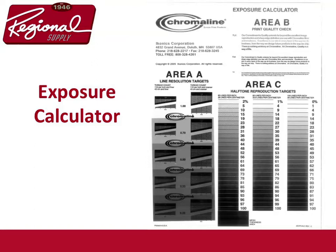Now, we have a lot of people ask, how long should I expose a screen? Well, it's really kind of a loaded question based off what kind of exposure unit you're using, how old your lamps are, what kind of emulsion you use, ProCap, how thick your ProCap was, and the thickness of your stencil. So using an exposure calculator like this, if I take an estimated guess that I've got a 5-minute exposure time, I'll double that and start with 10 minutes using this calculator and expose it for 10 minutes. Then when I go to the washout, I can look at this chart, and the one in the middle, the 0.5, is the one that washes out the best and gives you the best resolution. Then I just take that 10 minutes times 0.5, and 5 minutes would be my ultimate exposure time.